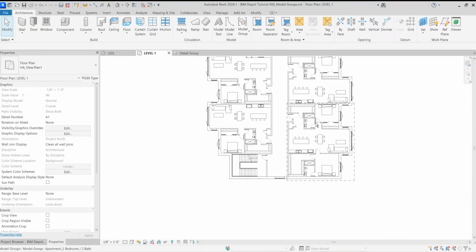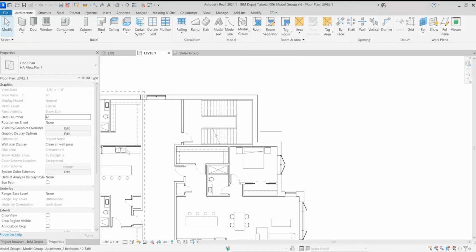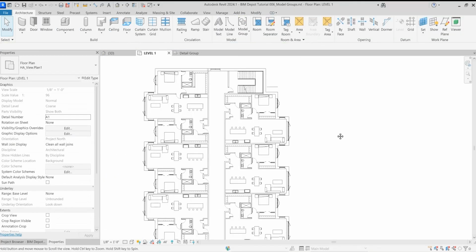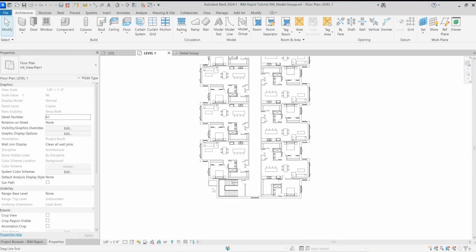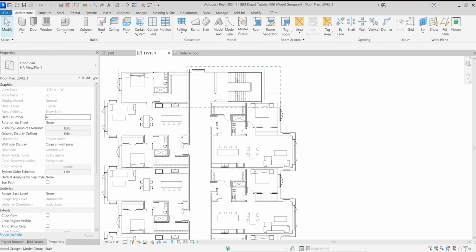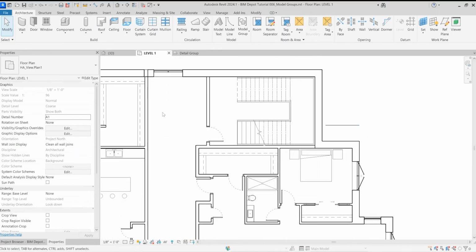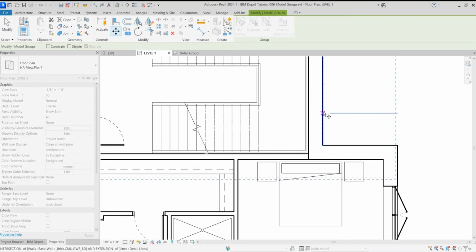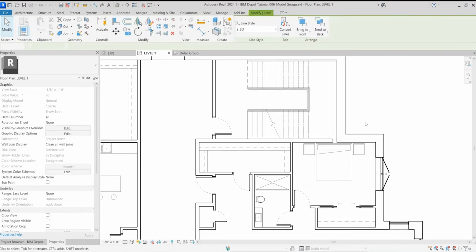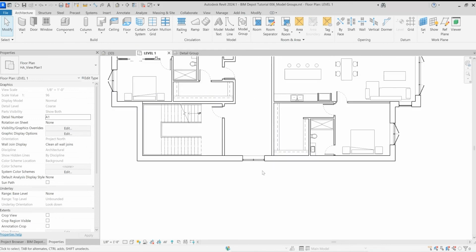Let's make sure that didn't modify this down here. Oh, so it did modify this. So I see here, this is sort of what I was saying previously, with clean modeling and making sure you're doing things accurately. It looks like when I copied this over originally, I must have moved one of the instances such that it no longer is symmetrical and consistent with the rest of the building. So if we click on this, type in move, we can actually move this such that it's consistent with the other side. And now we'll notice that the wall is good on the north side and good on the south side.